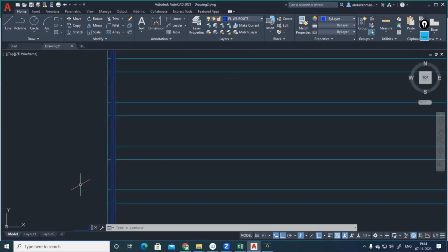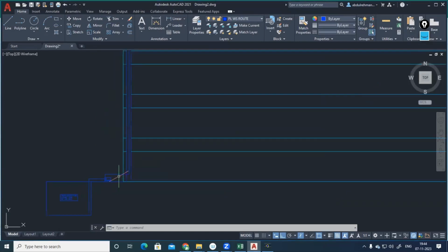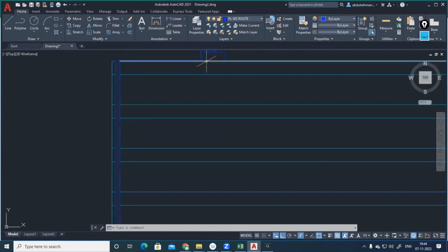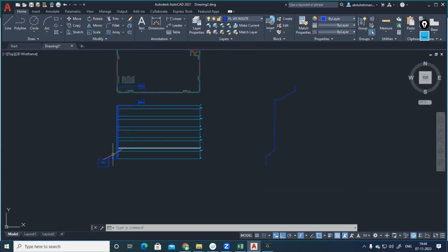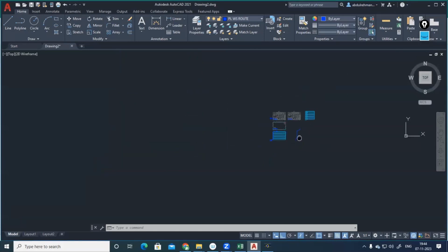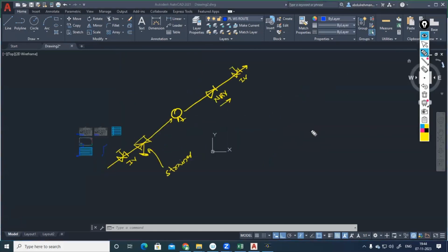You can see the pump will start and deliver the water until here. All of a sudden, if the pump stops, the water in the vertical column, the vertical line, will come back to the tank again. That has to be prevented, right? Water should not come back to the tank, and then the pump has to work again. Correct. That's why the pump delivery side always will have an NRV.